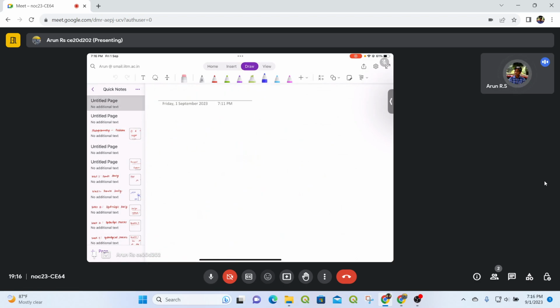Now let's go to the concept of relief displacement. Relief displacement I have already taken in the first week. So now I will show you how to derive that. Let us say this is our exposure station, and let's say this is the positive plate of your photograph. Now we have our tower.